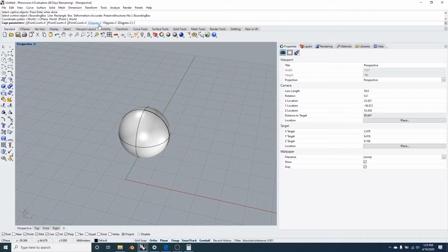The degrees, it's dealing with the amount of curvature that you're applying to your object. For us, 3 is enough. If you decrease this, your surface might become a little bit tessellated. So that applies to the X degree, Y degree, and Z degree. So we're going to leave it at the default of 3 for all of them.